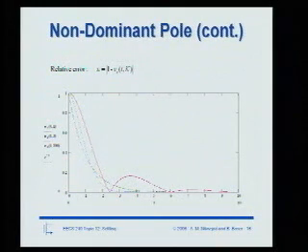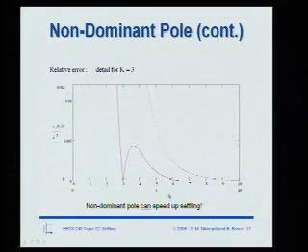All right. Well, the interesting observation, though, is that this factor of 3 seems to be pretty close to optimal. And here's a zoom in again for what's happening. This is the k equals 3 again. This is the normal. So this is a zoom in. This is 1% accuracy. This is 0.5% accuracy, and so on. You can see that, yeah, the k equals 3 does overshoot, but it overshoots so little that if you are trying to target, let's say, an accuracy level of about 0.5%, already at 3 time constants you're pretty safely there.